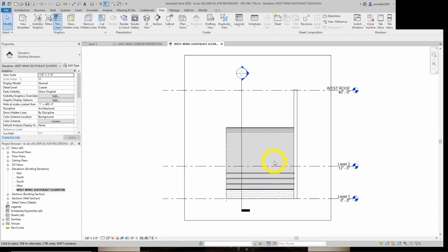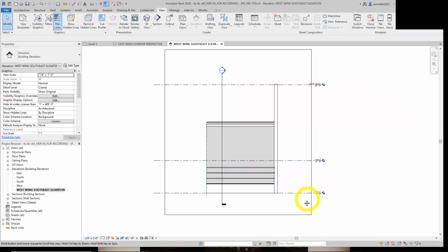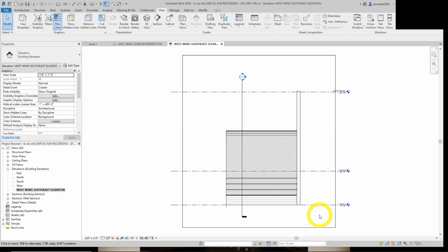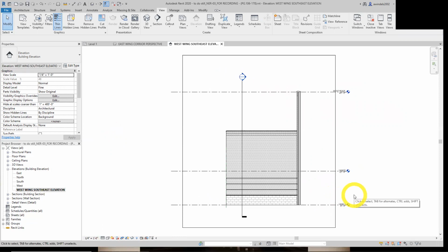You can see there's a little cut of that area. And change the annotation scale like they want, just to get you used to doing this how you need. Click, and let's do define too. Increase the detail level. And yeah, we got that view now as an elevation view option.